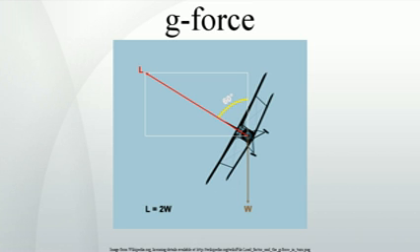Measuring G-force using an accelerometer. An accelerometer, in its simplest form, is a damped mass on the end of a spring, with some way of measuring how far the mass has moved on the spring in a particular direction, called an axis. Accelerometers are often calibrated to measure G-force along one or more axes.